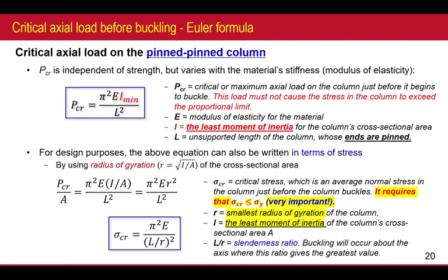But remember, all are the same. Just remember the highlighted part that requires sigma CR to be less than sigma Y, and this is very important. So please don't ignore this part. In the calculations, you must verify this part. Otherwise, there's no meaning to your work. Everyone clear? That's why I highlight it again and again. It's so important for you to realize.